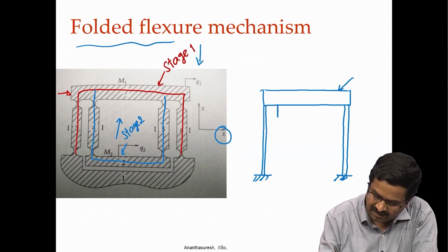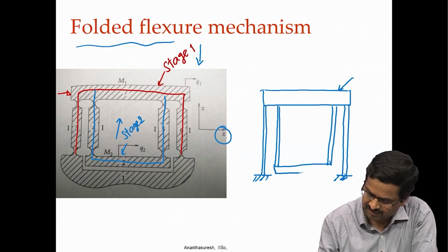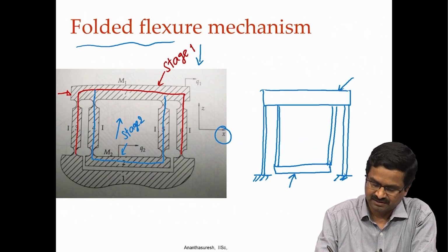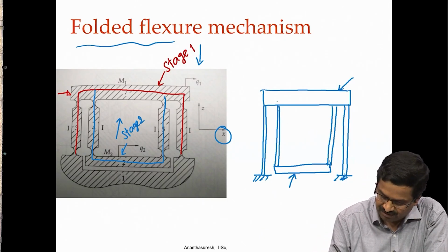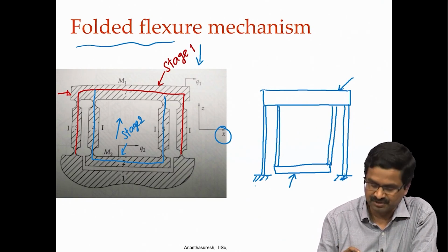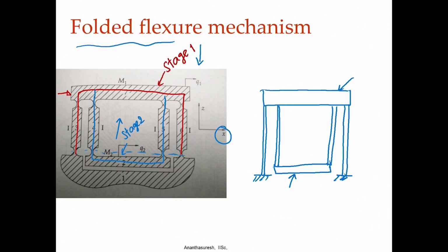So, we add another one here, another set of beams, a pair of beams. Now, attach the block. Now, this stage 2, if you dimension the beams, the beam lengths and the positioning of the second block relative to the first one, if you do it right as it is done here, they should all be aligned, okay, which I have not done in what I have drawn. So, if we do that, this one is going to purely translate.